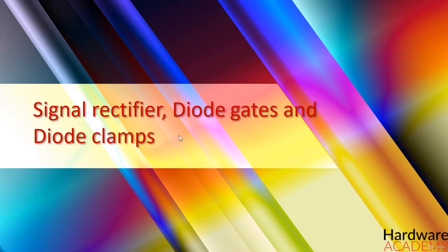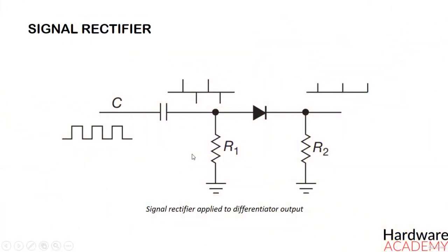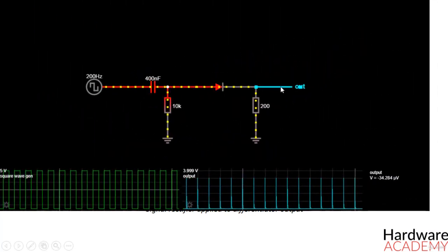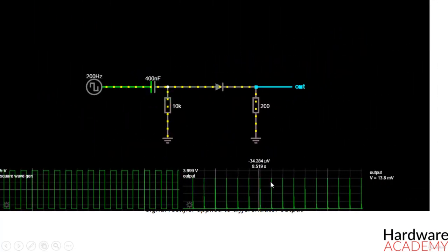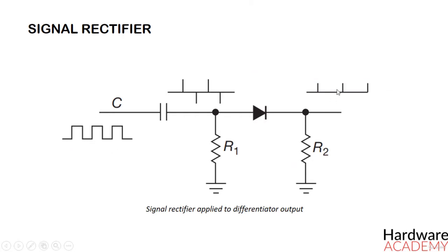If the input waveform isn't a sine wave, you usually don't think of it as a rectification in the sense of a power supply. For instance, you might want a train of pulses corresponding to the rising edge of a square wave. The easiest way is to rectify the differentiated wave like in figure here. Always keep in mind the 0.6 volts approximately forward drop of the diode. This circuit, for instance, gives no output for square waves smaller than 0.6 volts peak to peak.